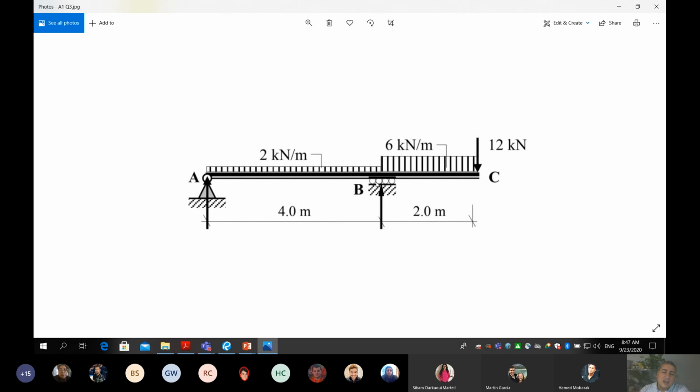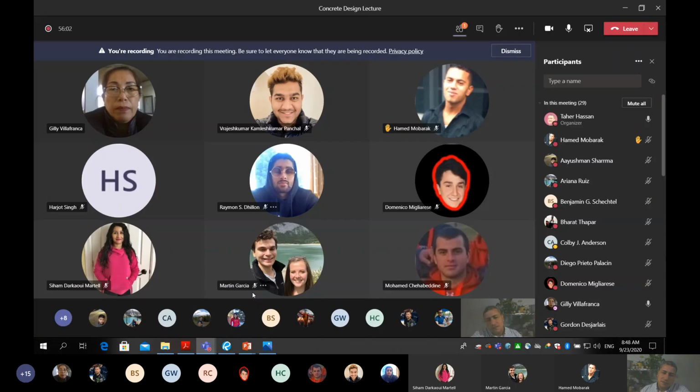That's not really handy when we do structural analysis. That's why when we estimate the load, we try to estimate the load per linear meter on the beam, and then we place this load on the beam in SAFI to find the bending moment, shear and axial force. Does it make sense? Makes perfect sense. Thank you. And by the way, Martin, when the time comes and you have enough information about slabs, I will give you the answer to that question about the slabs.